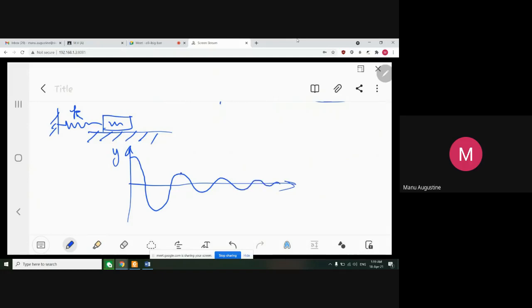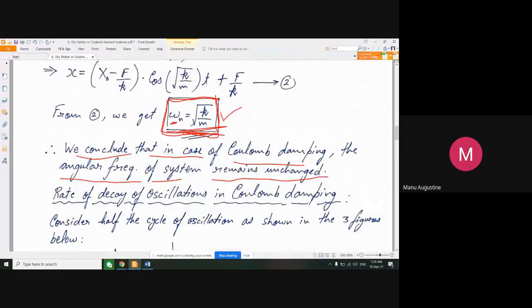But once again, you ask this question, what will be the distance between the two consecutive crests in this decreasing amplitude scenario? You will say that this, this being the time axis, is the time period, and you were expecting some omega d here. You were expecting that due to damping, the natural frequency would be omega d and not equal to omega n. So you were going to claim that this time period will be given by 2 pi by omega d. But this is what we found out here,